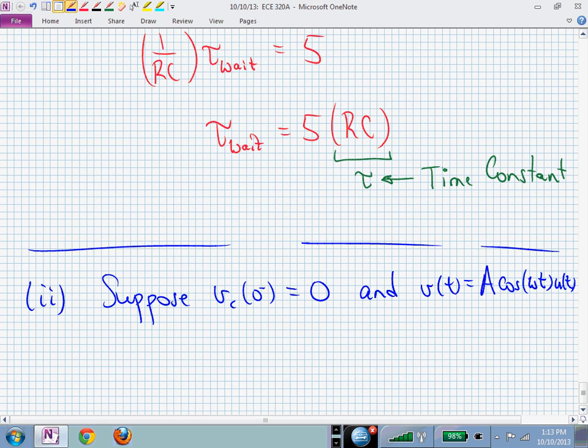And I'm not going to specify the frequency. I want to keep that variable so that you can kind of see where that variable frequency comes into play. But now omega could be 10 radians per second. It might be 1,000 radians per second. If I gave you an input and I said, oh, I need to excite this circuit with a 60 hertz waveform, what's omega? 377, thank you. 2 pi times 60, right?